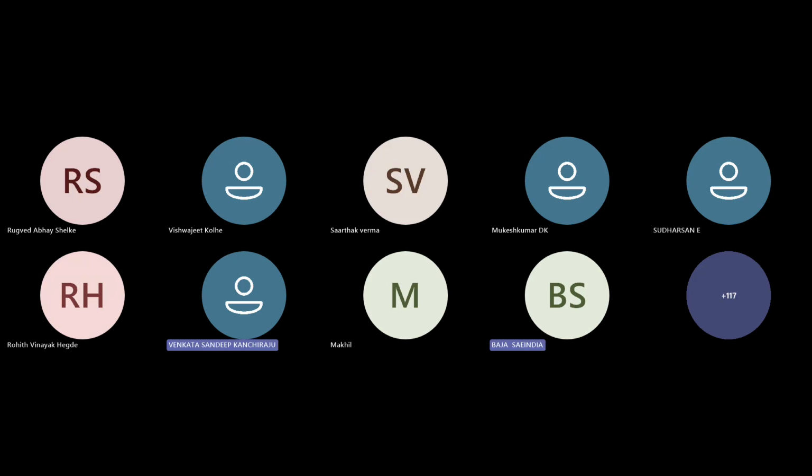Should the vehicle geometry created in SolidWorks contain the suspension free or locked while importing in IPG? This is for the OBJ, right? The OBJ is totally for visual purposes. It does not reflect any of your parameters representing a car model. So it should not be the dynamic model while creating a vehicle, but there are no constraints on the same. You can use any vehicle model from SolidWorks.